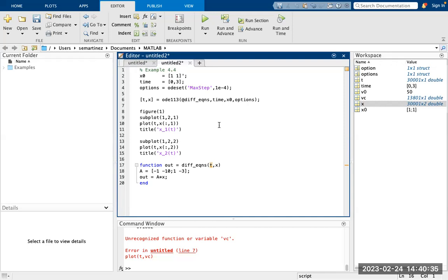That's one approach, right? So you have to model the grid. That is what is behind that. And you already kind of studied how to model the grid: the admittance matrix, the relationship between the angles and the voltages at each bus with the active power injected and reactive power injected.